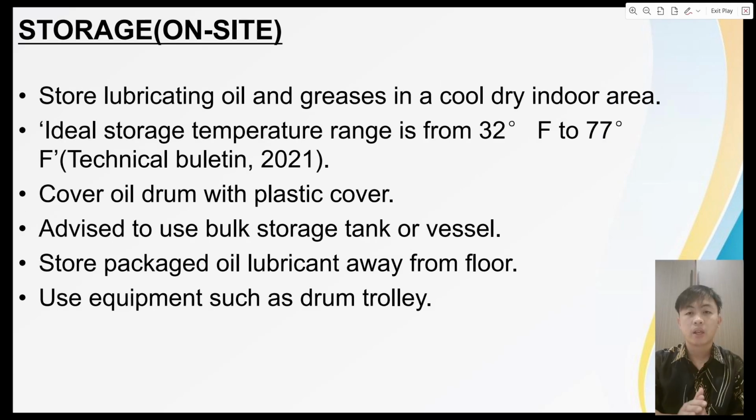This is for the second point. The second point is storage, on-site and off-site. For on-site, first, store lubricating oil and grease in a cool, dry area to avoid label and container deterioration.